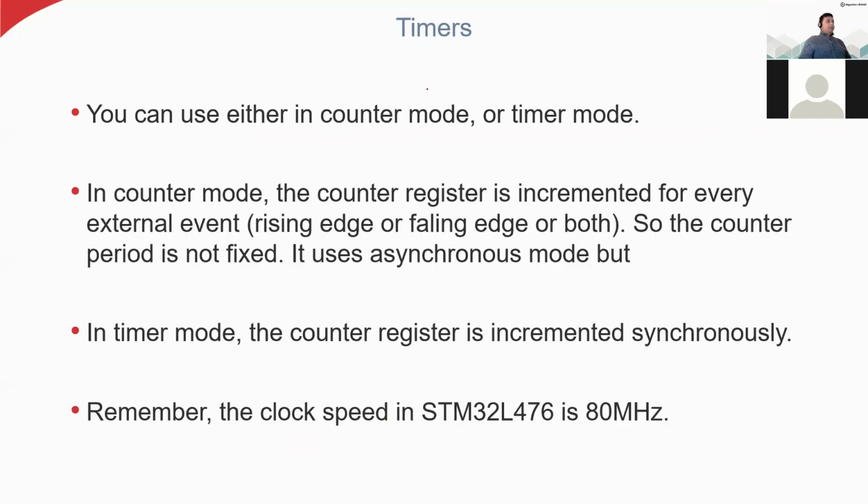Use it either in counter mode or timer mode. So as I mentioned, everything is just registers, and you are going to use them either as a timer or counter. In counter mode, the counter register is incremented for every external event, that is the clock signal, because the clock signal is synchronizing the counting between the registers.